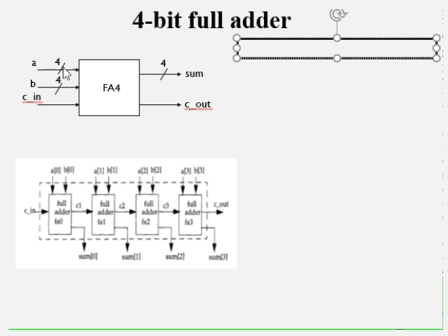So it will have two numbers of 4 bits each, which I have given as A and B. The way in which we write vectors in the block diagram is, you write the input arrow indicating it's an input line, and A and B. These are the signal names, and to indicate that it is not a single line but multiple lines, we write a slash over that arrow and write the number of lines that it represents. It's a 4-bit number, so I write /4.